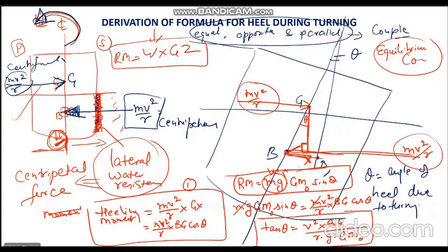What is this O in GMO? Down: initial metacentric height GM zero, upright condition. Instead of initial, I prefer to write zero because initial is confusing to people. They start using the words GM initial and GM final. GM initial is the GM when the vessel is upright. GM zero is same as GM initial. Okay, drawn the diagram, guys.